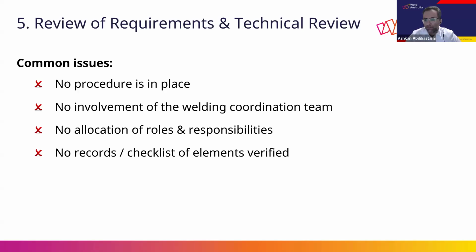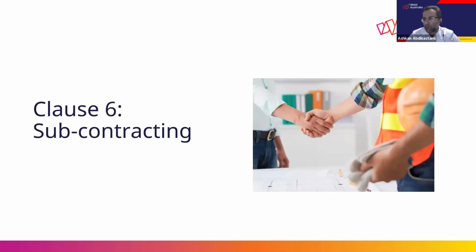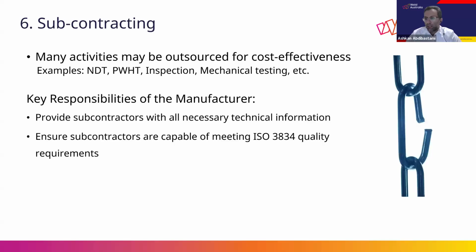Okay. Clause 6, subcontracting. Subcontracting is common for activities like NDT, post-weld heat treatment, inspection, or testing due to cost and convenience. But the manufacturer remains responsible and must provide subcontractors with all necessary technical information and ensure they are capable of meeting the requirements of ISO 3834.